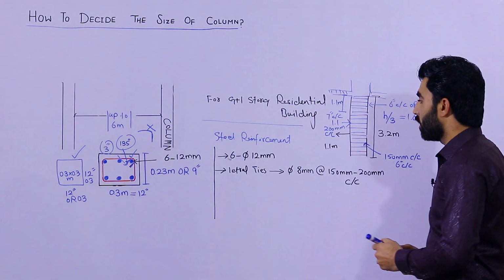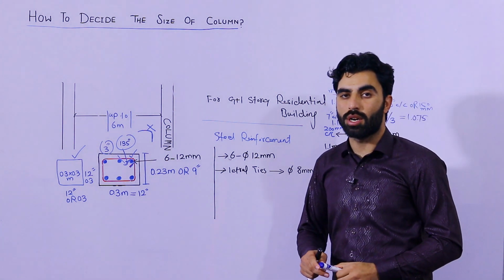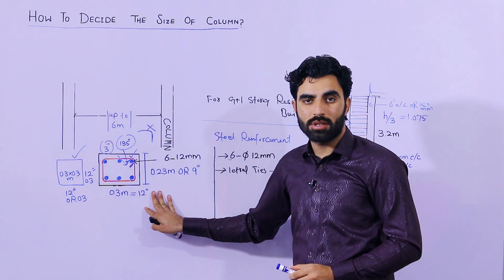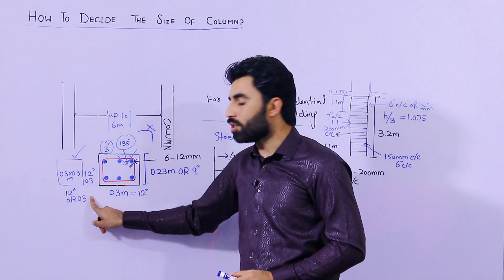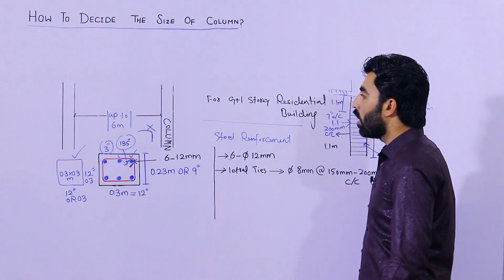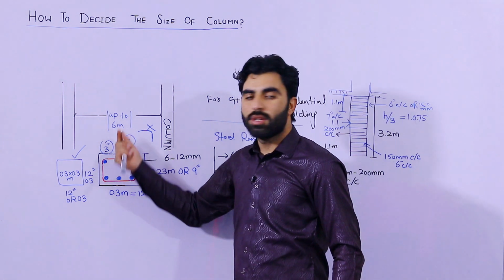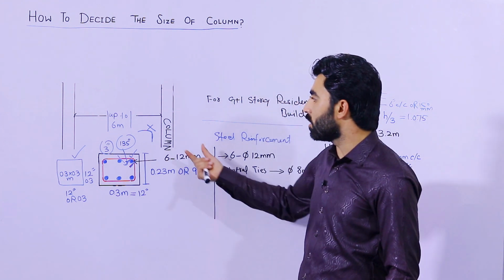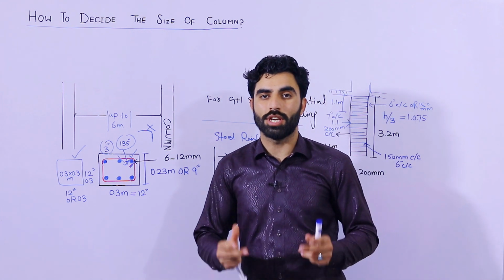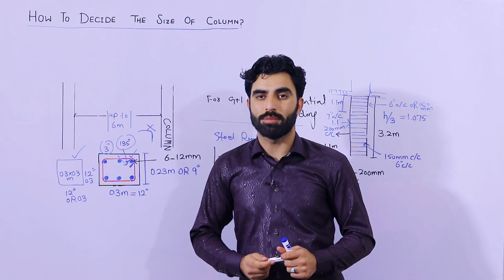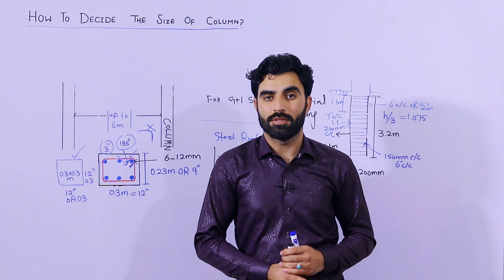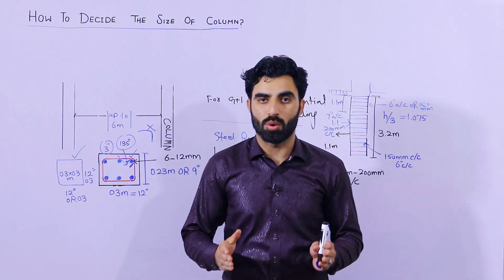So these are steel reinforcement details for G+1 story or 2 story residential building, and this is the size, minimum 9 by 12 inches, but I am recommending 0.3 by 0.3 or 30 by 30 centimeter for G+1 story, up to span of 6 meter, okay. If you want to increase the distance between two columns, you can't use this design which I have discussed in front of you. For that we will do the proper steel structural drawing, because design of column, design of beam, size of footing and steel reinforcement all depend on the structural load of the building.